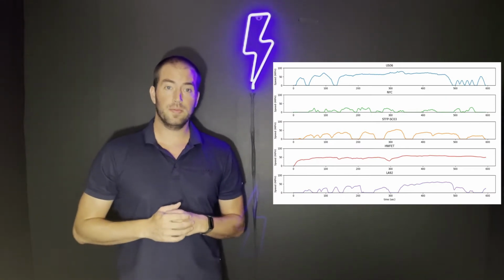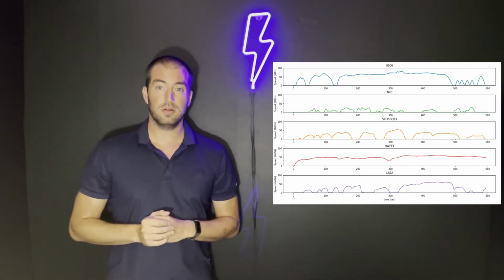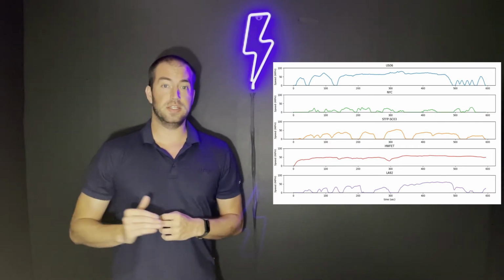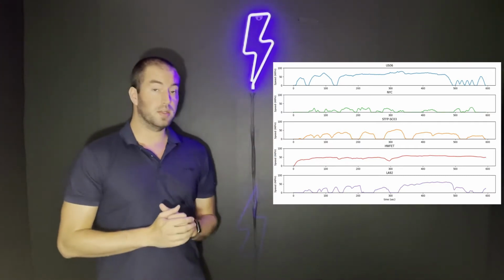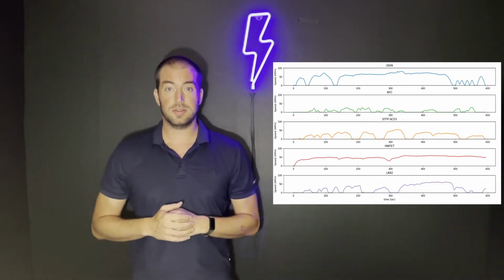This is going to tell us how far my car can go in city and how far it can go in highway. In this certification test, we're going to start with the vehicle having a full battery, and we're going to run that vehicle from full to empty through this series of different drive cycles. We're going to run these at city, at highway, and look at the different conditions.